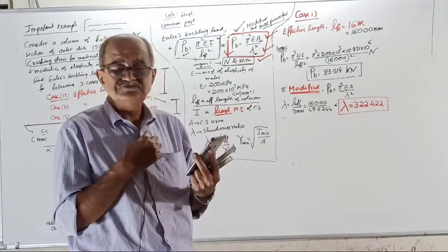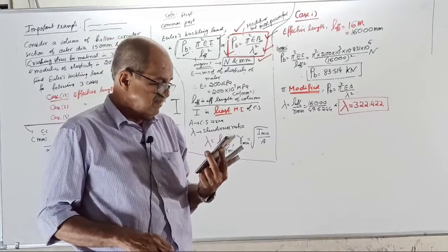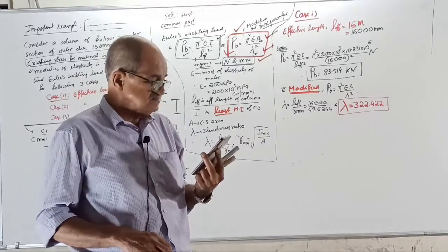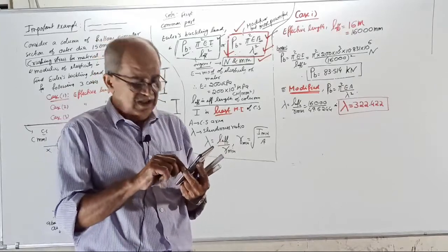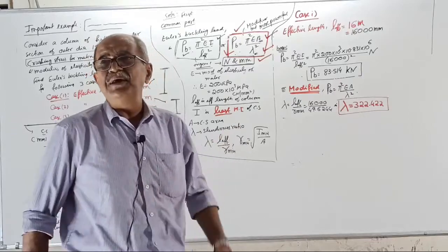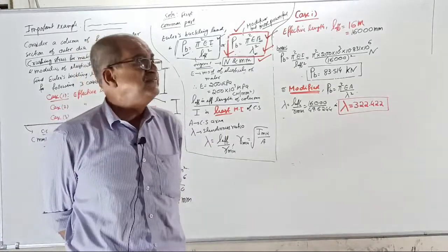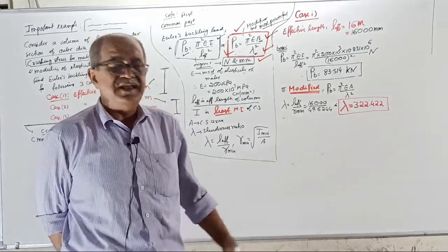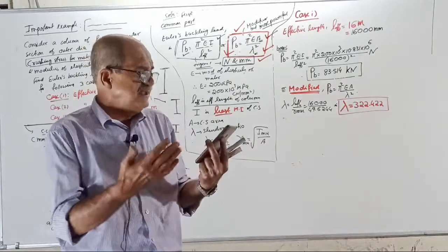Forgot so fast. All steel forgotten. It is not 80. 80 is usual. If you go for ISMB 300 or 400, when the height of the column is around 3 to 5 meter, lambda will come around 80. That is no problem. It can take around 100 tons load.